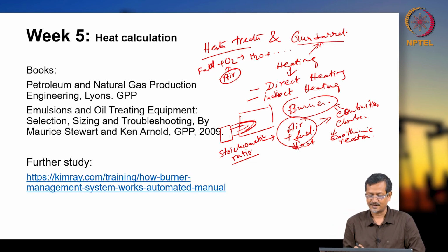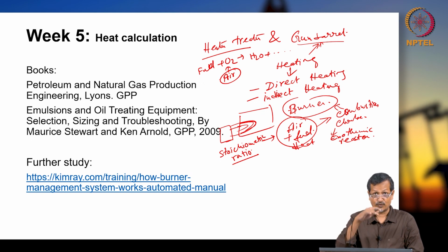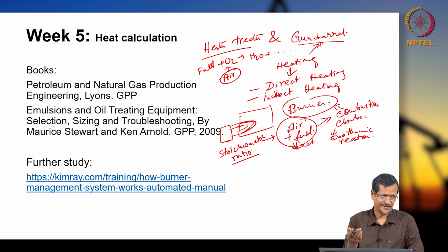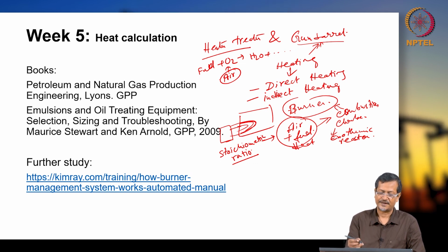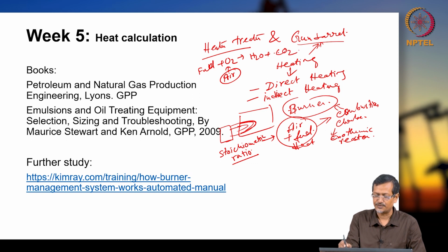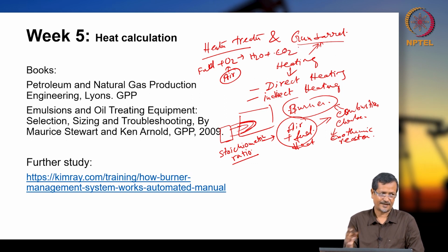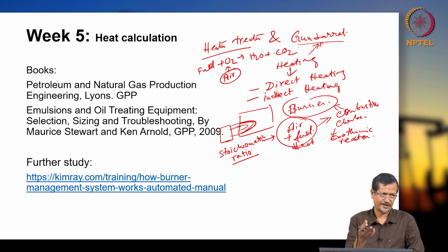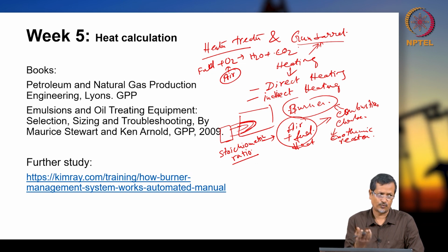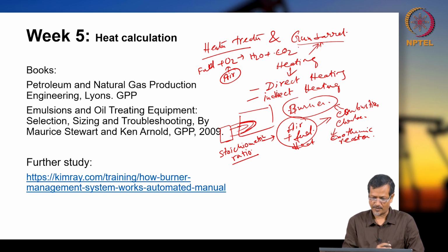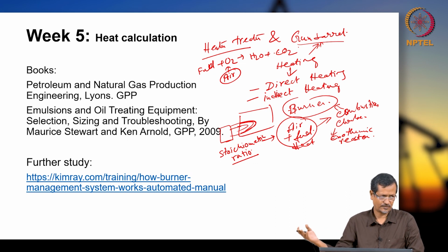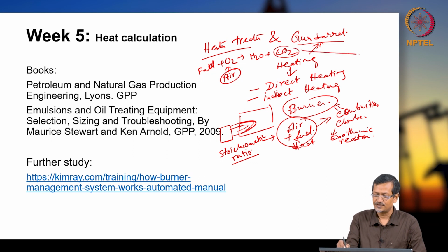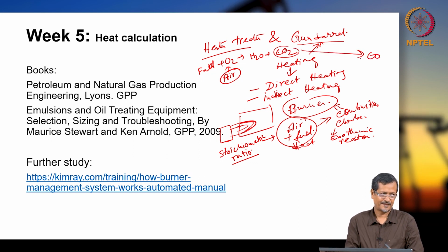Now some smart student can ask, sir, then we will put in a lower amount of air, so what will happen? If you put in a lower amount of air, the fuel will not burn completely, okay. After burning a hydrocarbon, it should produce CO2 after combustion, right? Hydrocarbon means petrol, diesel, kerosene, coal or wood; it will produce carbon dioxide, water and some other molecules. If you give a low amount of oxygen, instead of CO2 it will produce CO, carbon monoxide.